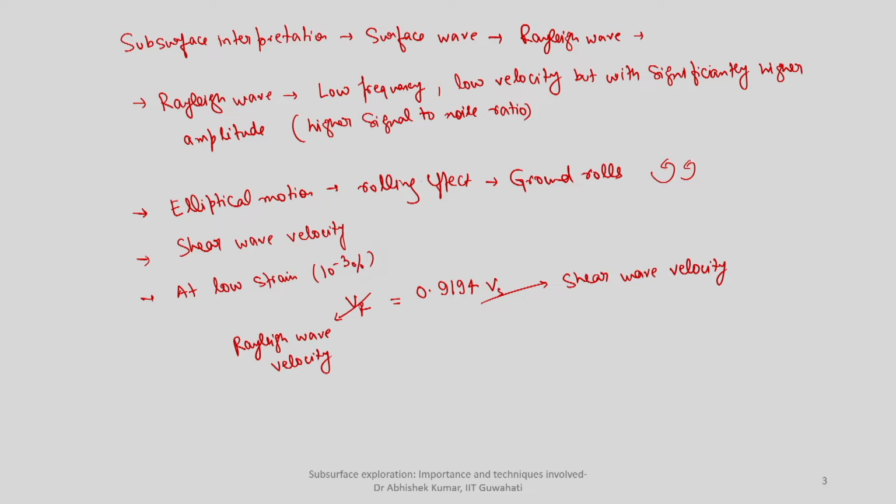And if you recall, based on your shear wave velocity or primary wave velocity, you will get an idea about what kind of medium exists below the ground surface. All these geophysical or seismic methods in particular do not get any sample and are often classified as non-destructive methods.